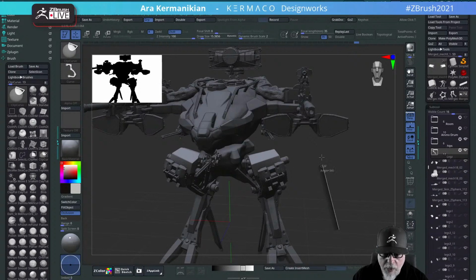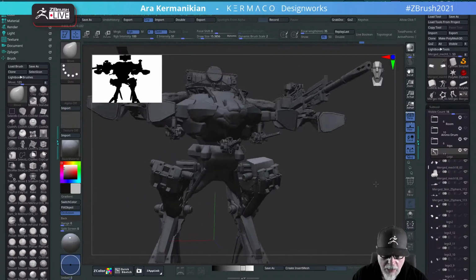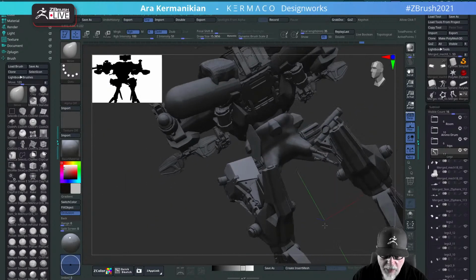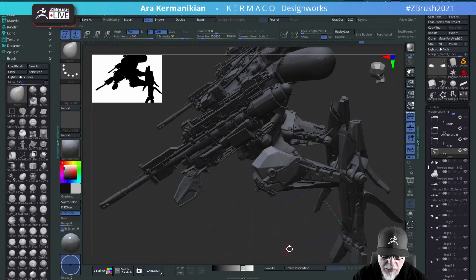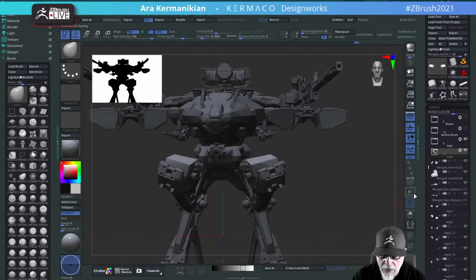But programs like Houdini and Maya do have limitations. So for that, you need lower subdivision level versions of the model, and then generate displacement maps or normal maps, and that will bring out some of the detail.